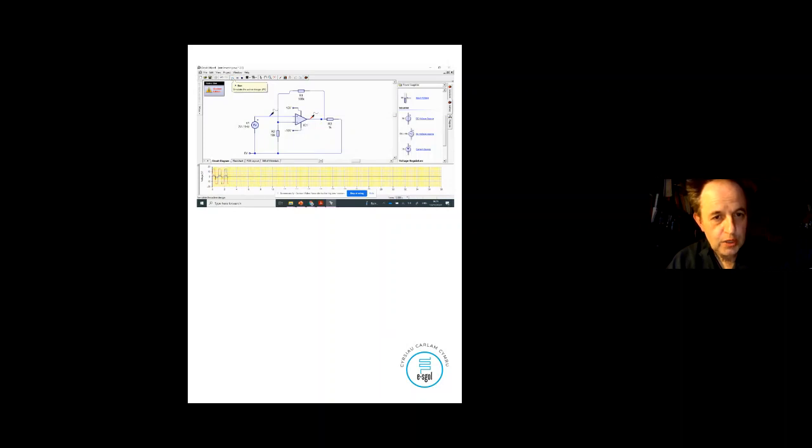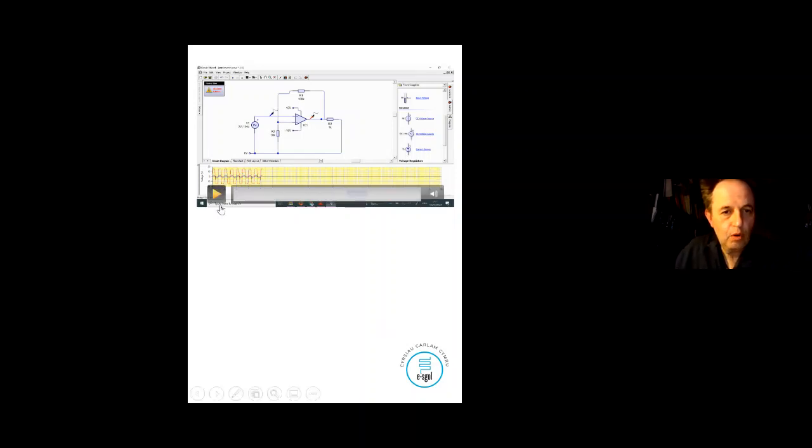And this one shows clipping distortion. Right? So it's a distorted signal because what the op-amp is trying to do is give an output greater than its saturation, but it can't. Right? So it will blow up. Right, so an op-amp will only give its maximum voltage, which happens to be its saturation level. So please be aware of that. So in this case, yeah, we've got clipping distortion. It can't give more than the saturation level.